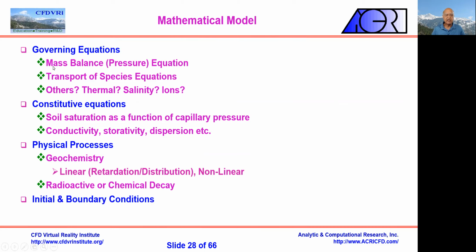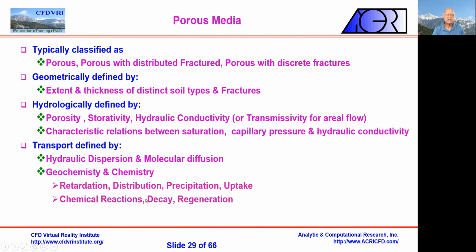The governing equations are the mass balance equations, transport of species equations, the pressure equation, okay, and the others such as thermal and salinity equations. The constitutive equations are the equations which give us the soil saturation as a function of pressure. Okay, we'll come to that in a minute. And then there are things such as conductivity, storativity, dispersion. I'll see what I can address here. I'll give you some idea. Okay, a lot of physical processes going on, and then we need initial and boundary conditions.